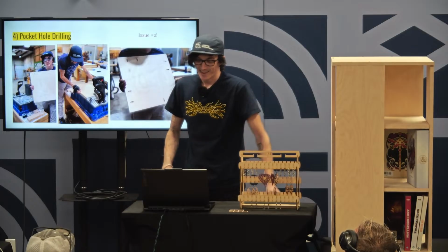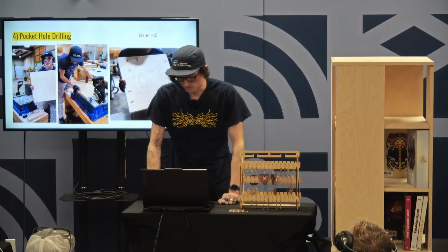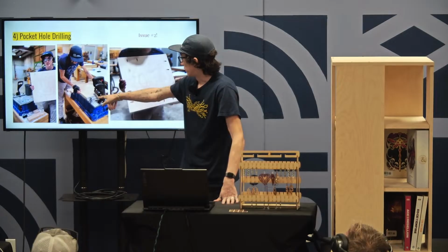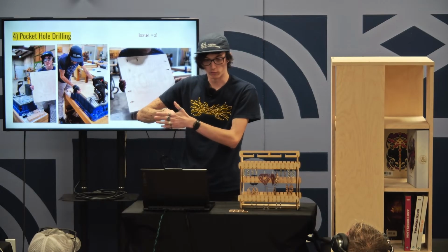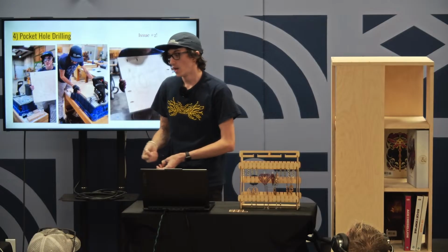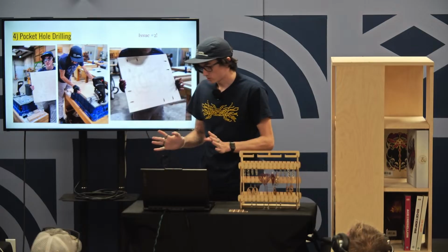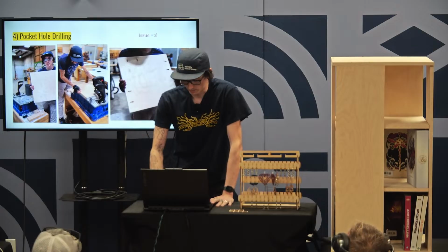And we ended up making all 16 of the pocket holes we needed to in like 20 minutes. It was fantastic. Issue number 2, however, is that we didn't do a test cut on a different sheet of plywood, and the pocket hole bit didn't go all the way through the edge of the edge banding the first time. So we had to realign some of our holes and re-drill them, which ended up not being a huge issue, but was just like, oh yeah, remember to do your test cuts.